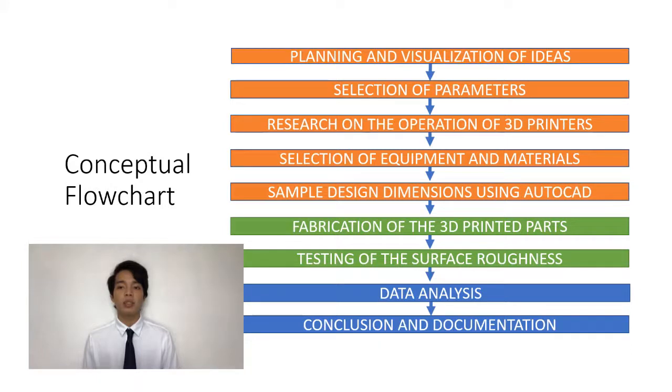We generated the combinations using response surface modeling in Minitab 17. We have 15 base runs and we replicated it 3 times, so we have a total of 45 runs. For the measurement test of surface roughness, we used the contact type surface roughness measuring instrument, which is the SurfTest SJ210. For the data analysis, we used the main effect, interaction plot, and contour plot to come up with a conclusion. These were the constant settings in the 3D printer used during the printing process.